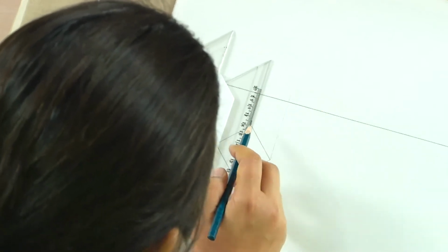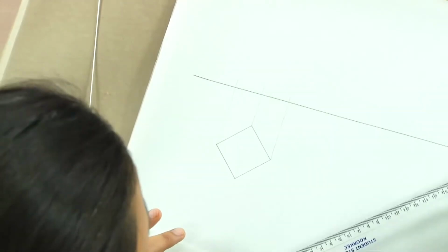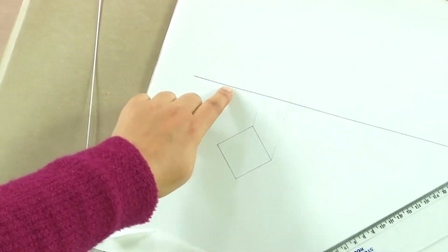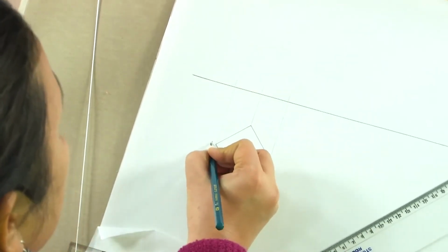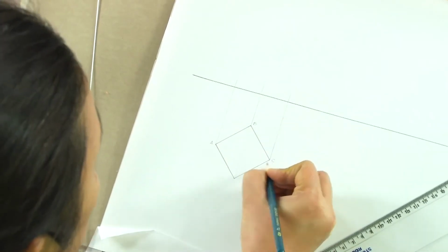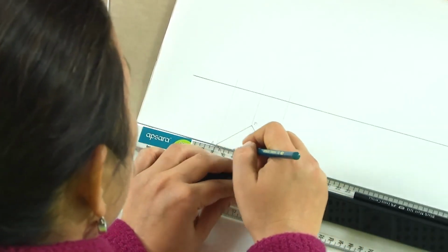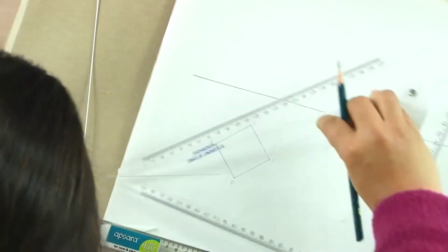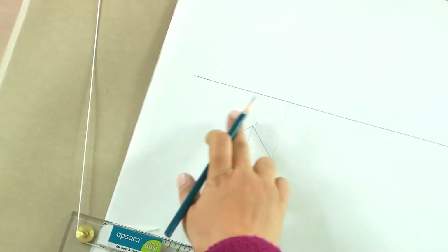So, this is not the final given condition, it is just the starting assumption that the plane is parallel to HP and it is perpendicular to VP. So, this is what we are seeing. I am very lightly labeling the square to start with. This is the square ABCD, and I will also draw the diagonals. AC is the diagonal and BD is another diagonal. So, this is what we are going to be drawing.